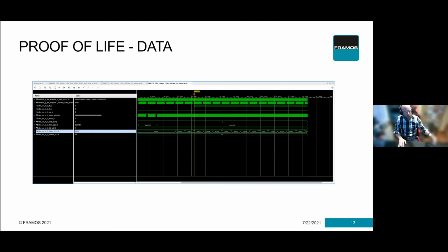I can then also correct your register set in this EVB language and send it back to you. But also, if you had that at your side, then you can do that yourself. And typically with these EVBs, you have some good information. This isn't a recommended design for most cameras if you check out how big these things are, but it is a good conceptual place to check on power consumption, heat generation, making sure that if a sensor on your system that you've desoldered had a problem, you can now stick it in an EVB after some cleaning to make sure that hardware is still working, aka was the issue with the sensor or was it with the PCB.